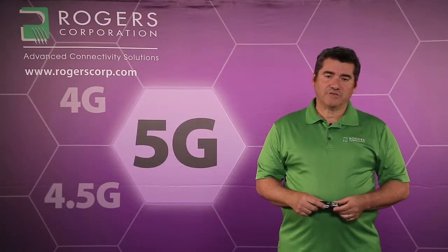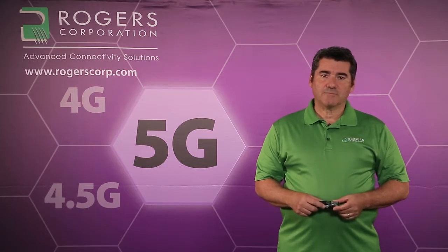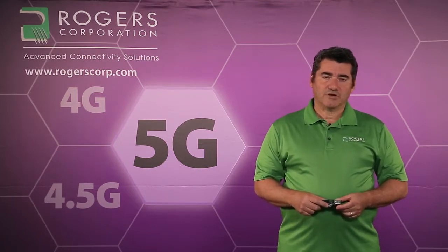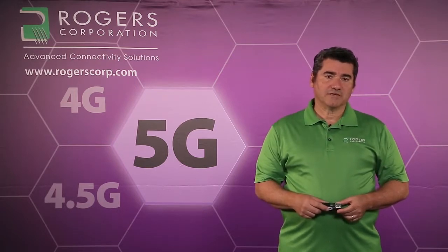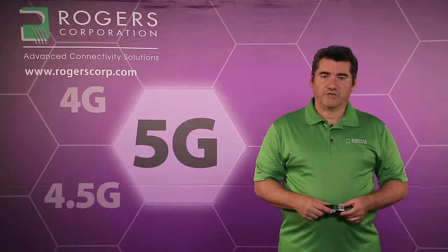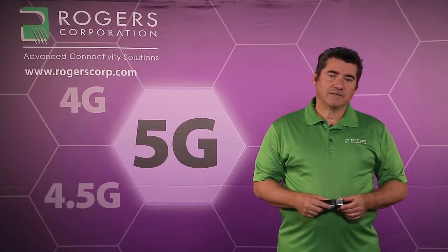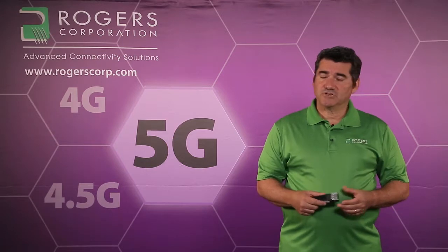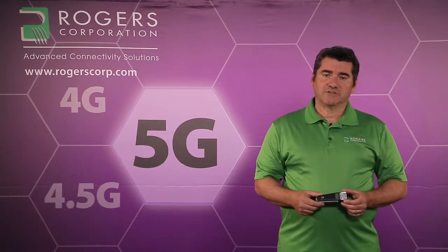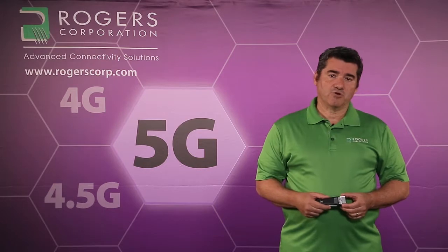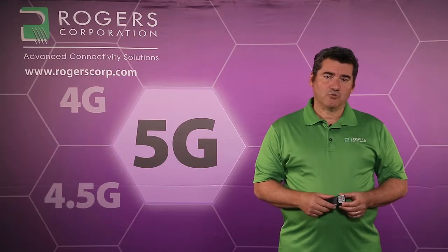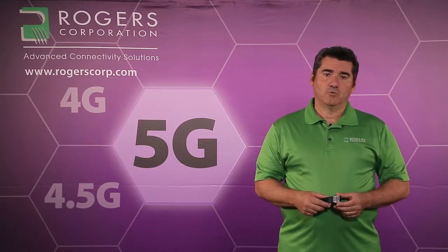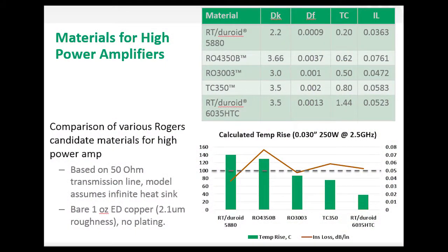When we talk about high power applications, many engineers usually think about low loss tangent materials. But in reality, what we're here to talk about is how thermal conductivity is the most important property when selecting a material for high frequency, high power applications. We're going to show you some data that compares RT-Duroid 5880, which is very, very low loss material, to some materials that have higher loss tangent but have a much higher thermal conductivity. In doing so, we hope to guide you in a direction to selecting high thermal conductivity as a primary property when selecting materials. In the table here, we have various materials that designers will use for high power applications.